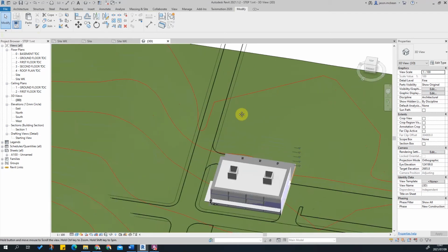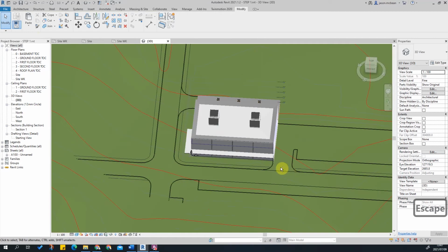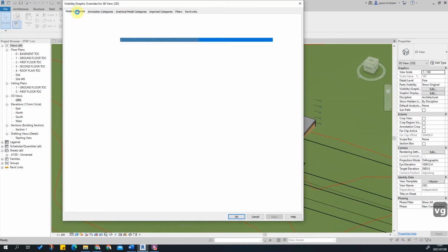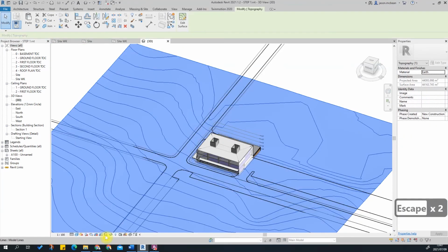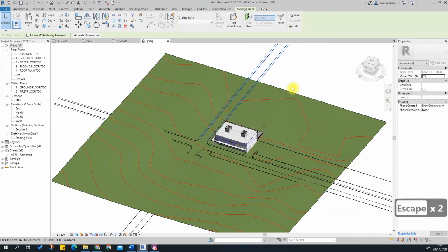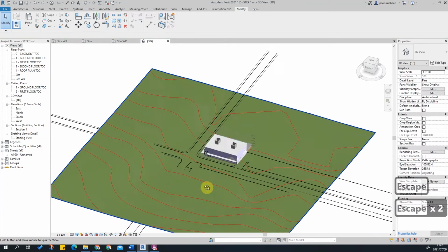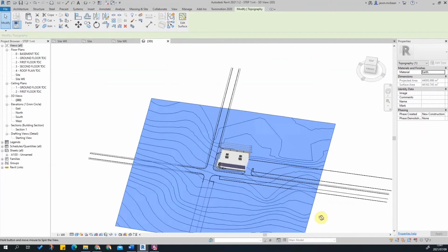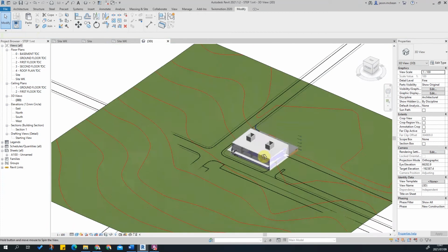Okay, the next thing I need to do is split the surfaces up, so where the parking is going to occur and all of those. So for now, I'm just going to switch off. You can switch off all the model items, that's totally up to you. But for example, I can just click isolate. So select all of the line work maybe. So you could select all this information, but ultimately all I need is the line work to help me cut out the road network on this topography. We use this in combination, especially later on if you want to export this to 3D view.